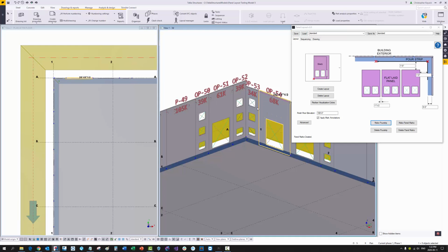Now, I can see here at a corner condition that we have 3 fairly heavy panels, and then we have 2 or 3 lighter panels. Now, if I have the crane towards the exterior, maybe I'm going to go ahead and do these light panels on a second interior row a little bit more towards the inside of the building, and I'll do these heavier panels at the edge. So I can actually select these 3 panels.